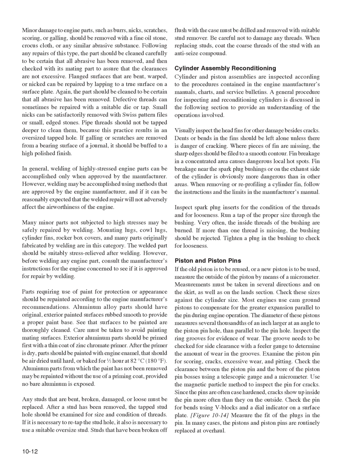Fin breakage in a concentrated area causes dangerous local hot spots. Fin breakage near the spark plug bushings or on the exhaust side of the cylinder is obviously more dangerous than in other areas. When removing or reprofiling a cylinder fin, follow the instructions and the limits in the manufacturer's manual.